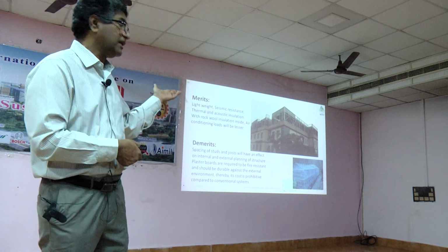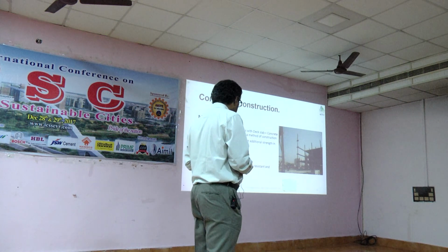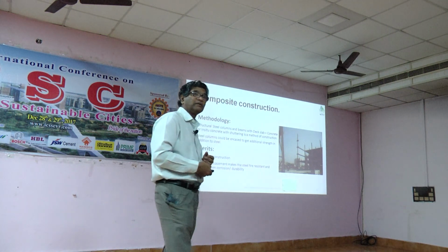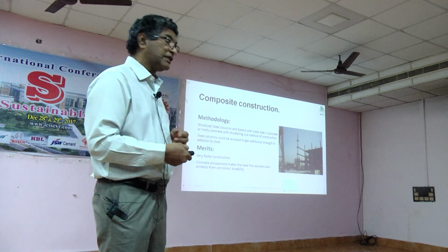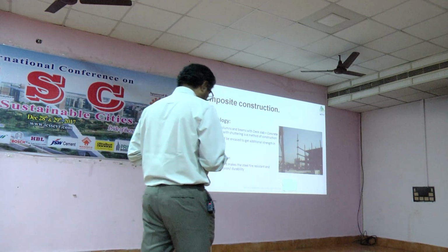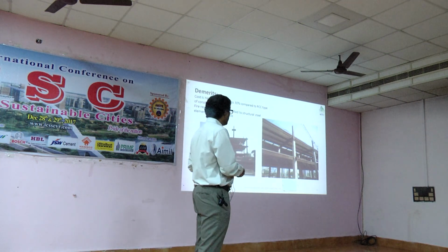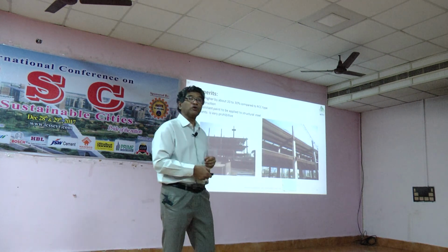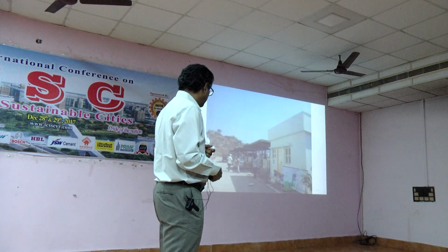With this light gauge steel, this case is quite easy to build. Composite construction nowadays is also happening everywhere, with steel and concrete slabs, and the steel columns are encased in concrete, thereby corrosion protection and fire protection happen automatically without the application of any paints and all.